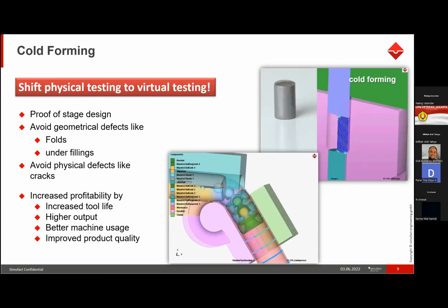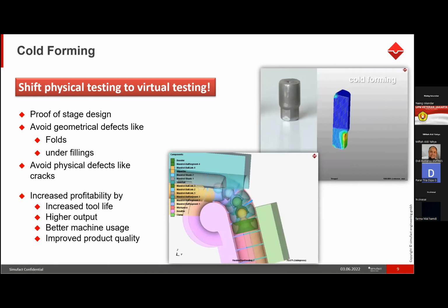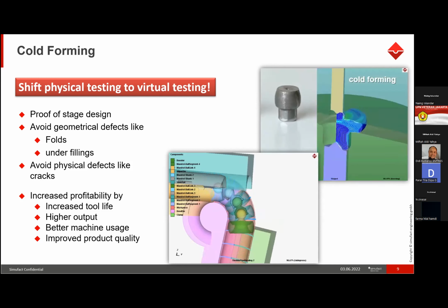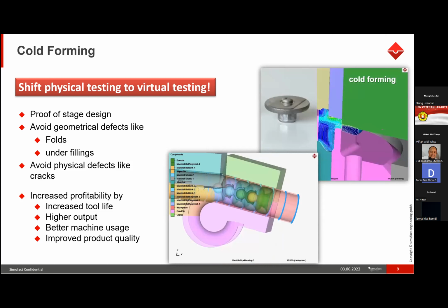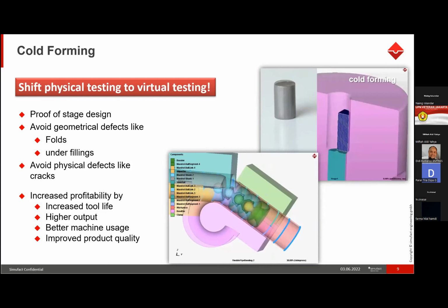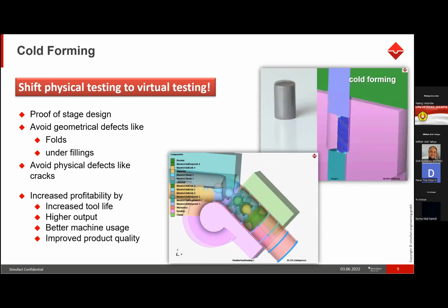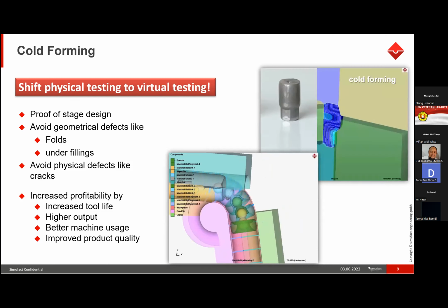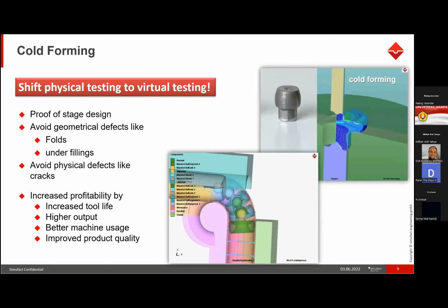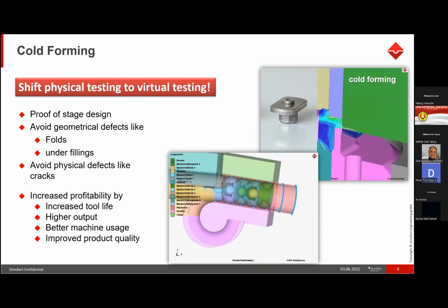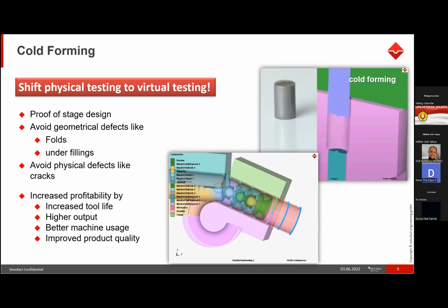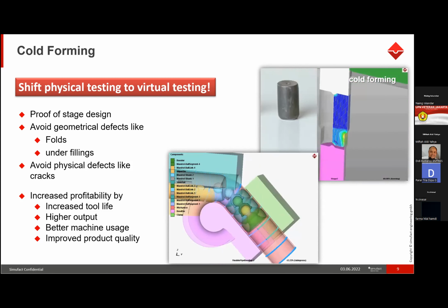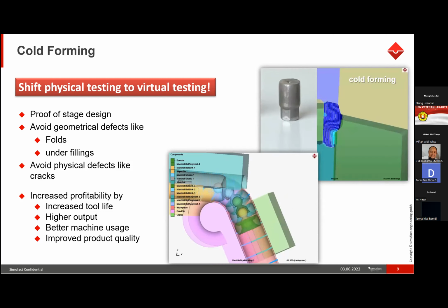And one really unique advantage with SIMUFACT is that you can have multiple tool kinematics. So there is no compromising on the tool kinematics. We can address every detail. For example, there are 4 tools moving in 4 directions, and you want to see how they will behave. So yes, you can specify individual motion for individual tool, and they will work independently. Or if you want them to move with a certain correlation, like with stiffness or spring loaded systems, those things also can be simulated in SIMUFACT.